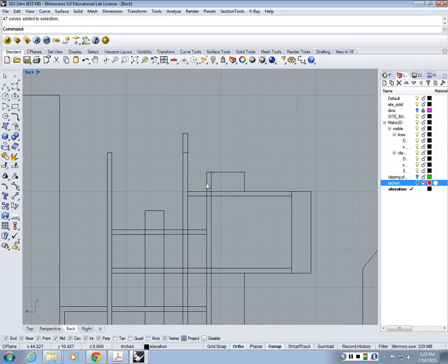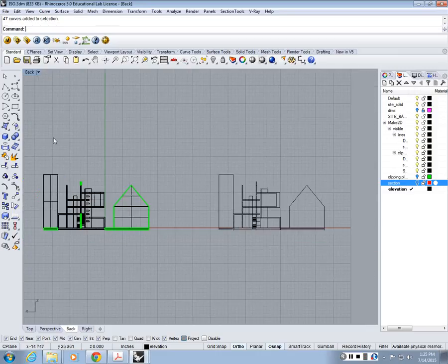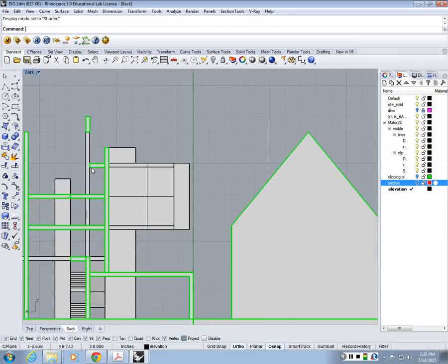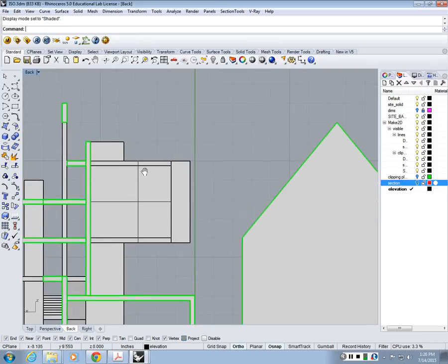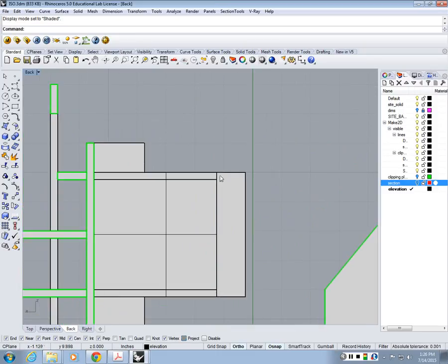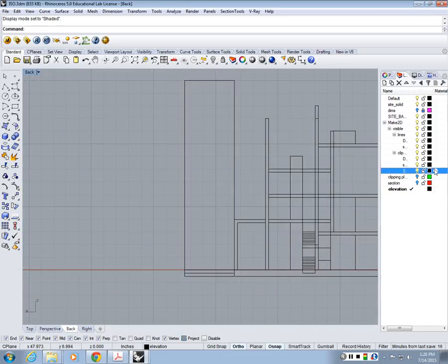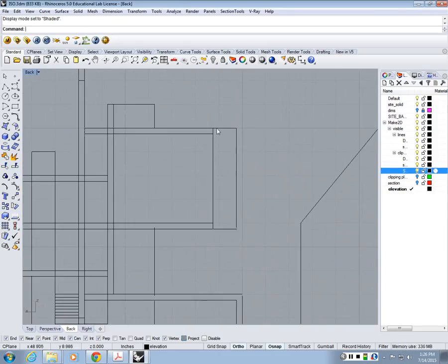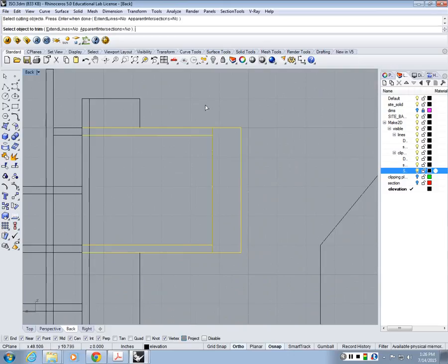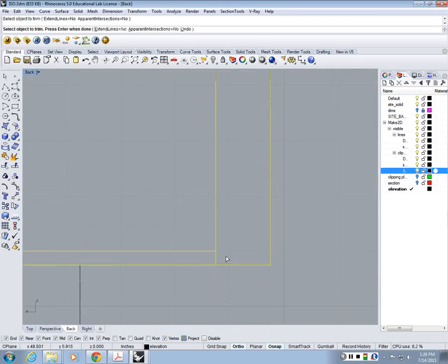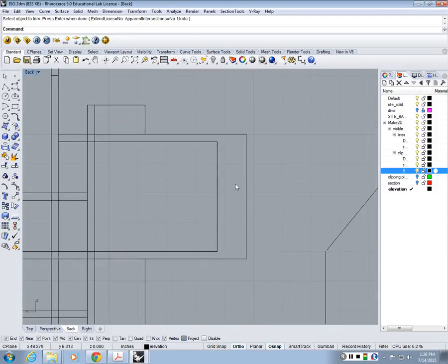So what kind of cleanup do we have to do? What we could do is look at our geometry and see if we need to join any type of surfaces. So in my model, these surfaces are basically flush. So what I need to do is I could just come in here and clean these lines, right? So I could just do trim again and delete these extensions, so this reads as a continuous surface.